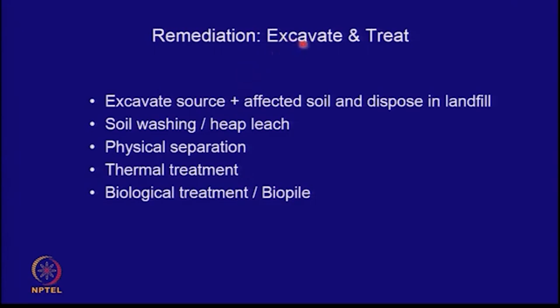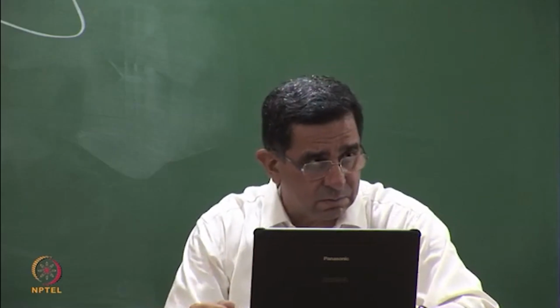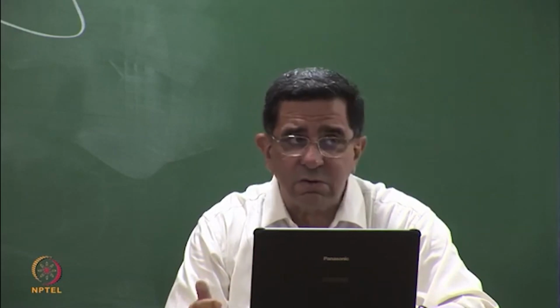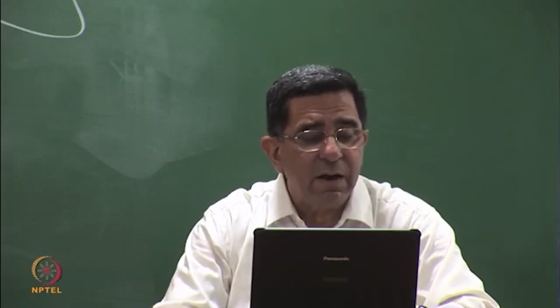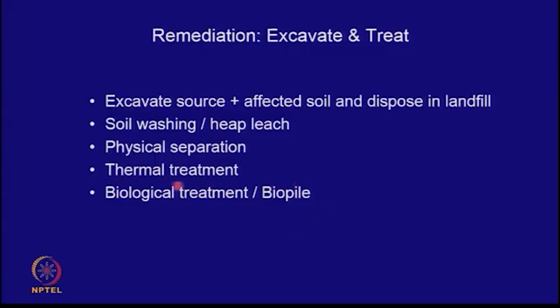Another treatment which is possible for small amounts is after you excavate the material is to incinerate it. So if you heat it, if it's got high volatile organics or if it has got some other organic compounds, you can incinerate it, and that will be another way of treatment. And finally, you may also do bioremediation or biological treatment by using some microorganisms. So one of the ways of tackling contamination of small sites is excavate and treat.